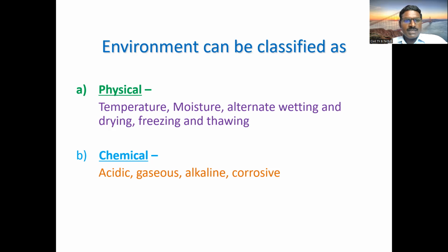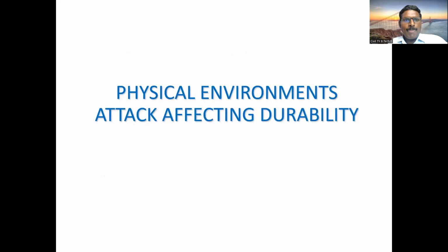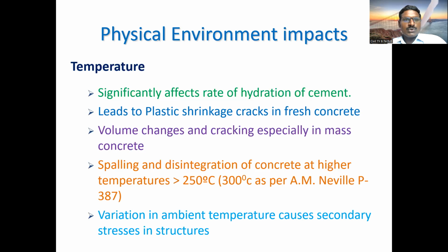Then chemical attacks will be there, that is acidic, alkaline, corrosive. So the physical environment attacks affect the durability. How will the physical environment attack the durability of the concrete? The temperature will affect the rate of hydration of the cement.